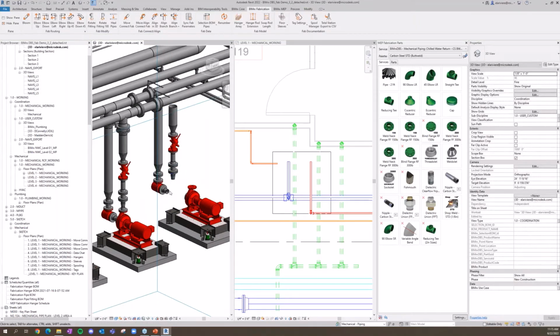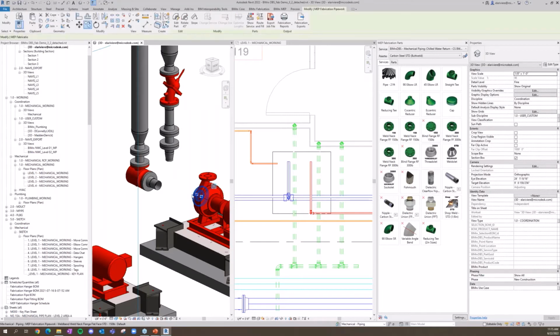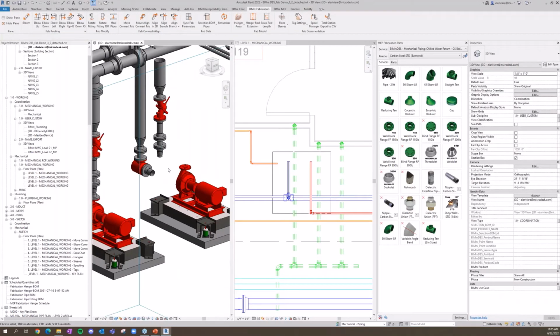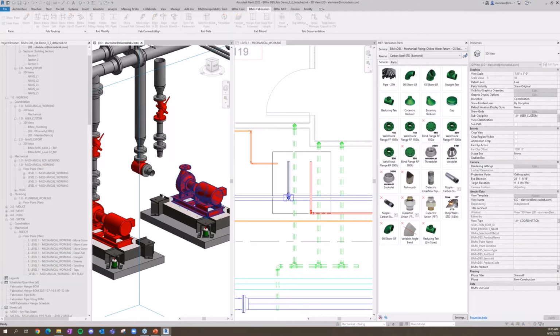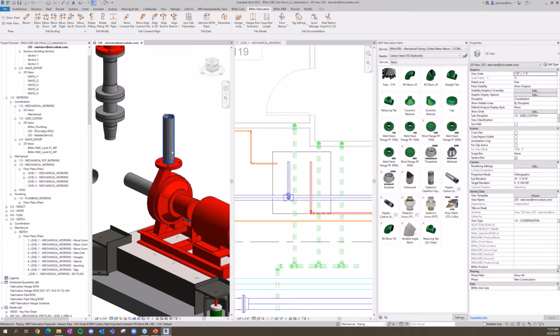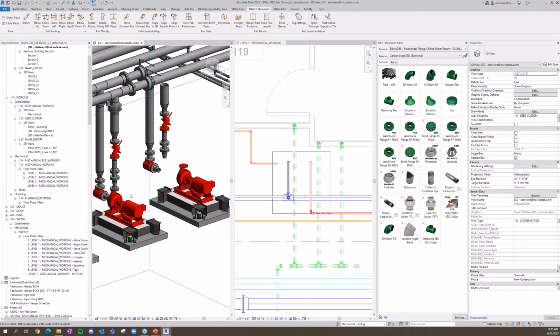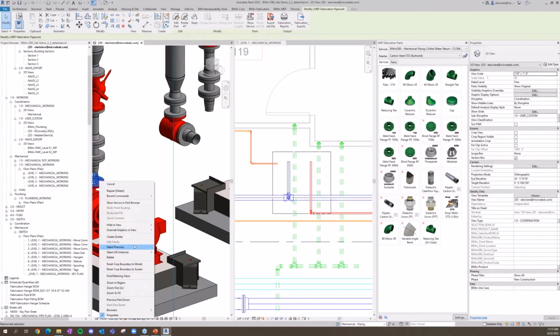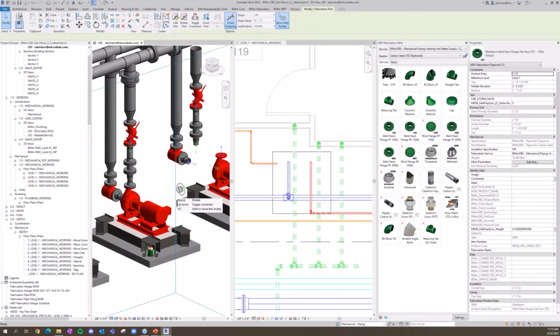Now you'll notice those flanges aren't coming. And I do have a flange here. Maybe I delete it. I'll show you something really quick we can do. So that bloom command that I was using on individual elements, we can do that on a piece of equipment. You will notice because I'm doing it on a piece of equipment that isn't already routed, it's not giving me the flanges, right? So in some circumstances, you may still need to do the very quick create similar and drop those flanges down, right? No big deal.